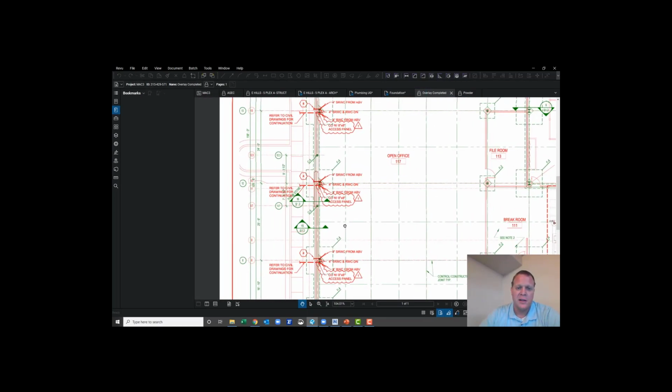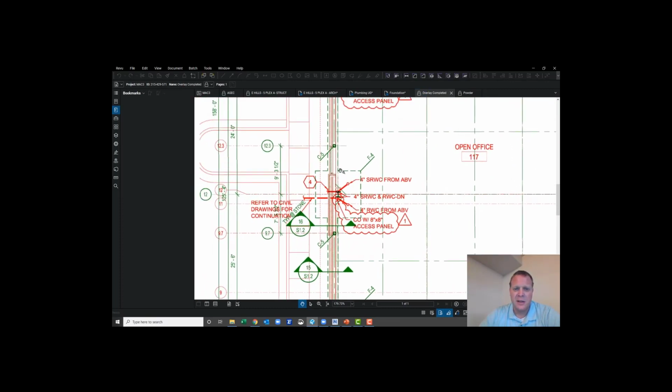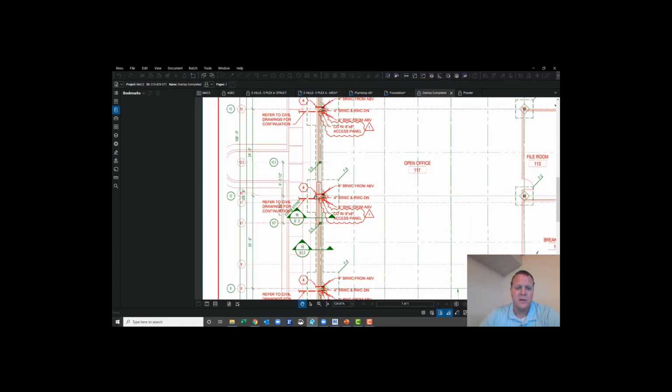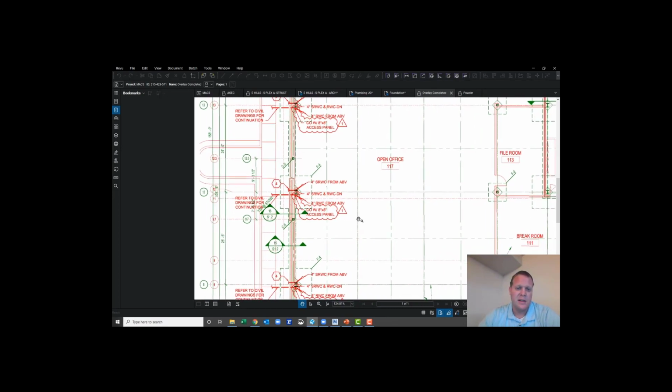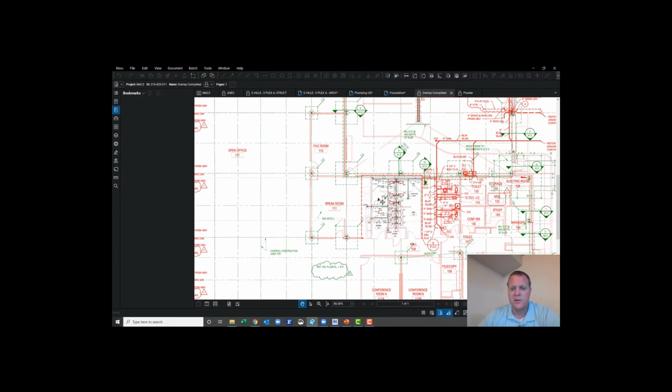We actually grabbed Bluebeam, overlaid the two drawings, and what you can see now is the green is the foundation, the red is the pipe, the plumbing, and we've got the conflict right there. And we gave them this drawing so that they could see easily what was going on both in the plumbing and below, plumbing and the foundation. And we attach this to the RFI. Give them that information. Now let's switch gears and look over here.